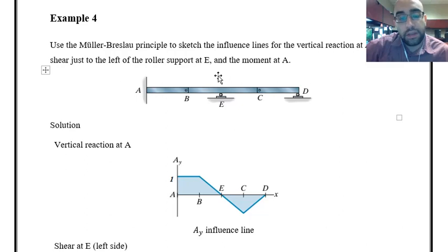The important thing is the hinge that we have over here. This hinge will help us to maintain the restrictions that we have at point A. So a unit displacement should be applied. I know on the right side it cannot have any displacement because of the support. On the left side we are going to have the whole displacement, and then at hinge B we can have the rotation.